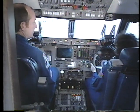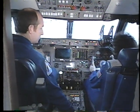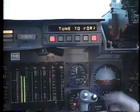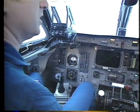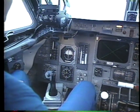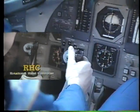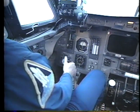A more obvious difference between the STA and the unmodified G2 can be found in the cockpit. The right side of the STA cockpit houses conventional airplane controls, along with instruments for monitoring the simulated approaches. The left side of the cockpit has been equipped with instruments and controls like those in the orbiter. One modification is the rotational hand controller, also known as the RHC. The RHC is used by the astronaut to fly the STA the same as the orbiter.